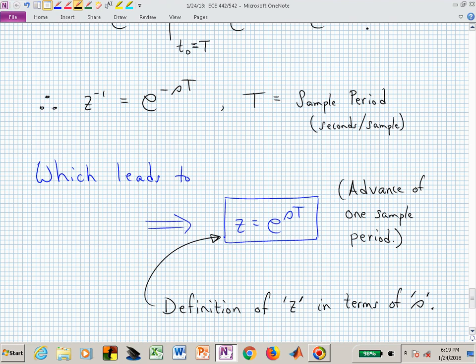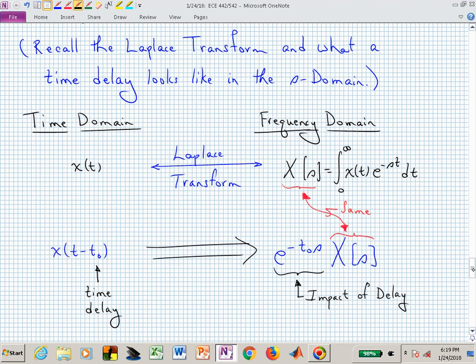So now the question is, where does this come from from a physical standpoint? Let's just focus on what we just talked about, which is this delay. The concept of a delay in Laplace was this e to the minus s some number. And that's how I would like you to think about where this e is coming from. It's what is present initially as our scaling or weighting amount in the definition of the Laplace transform, and that actually factors out when we introduce a delay.